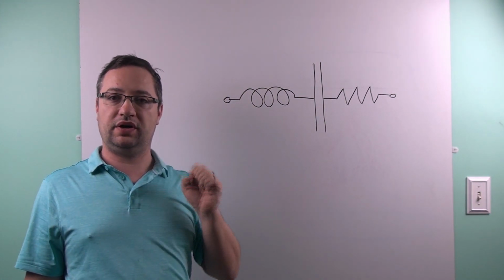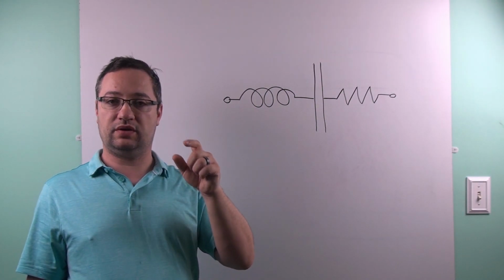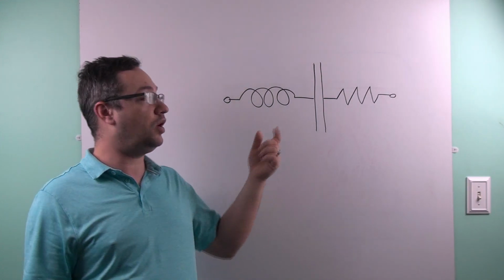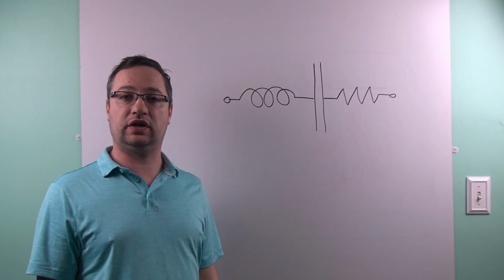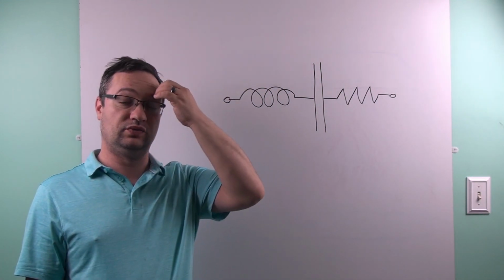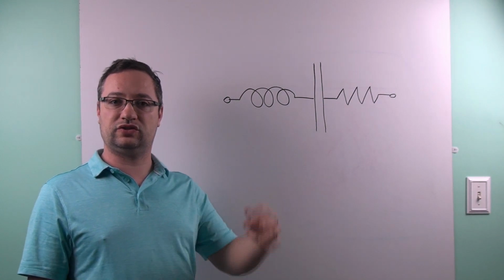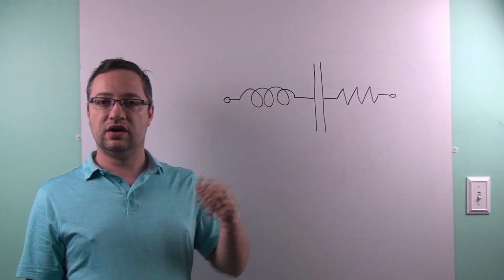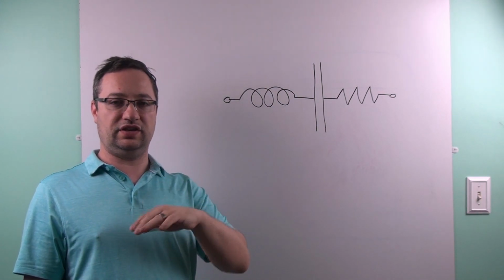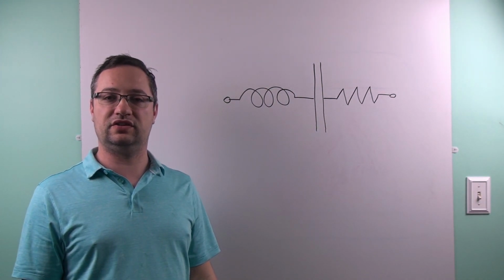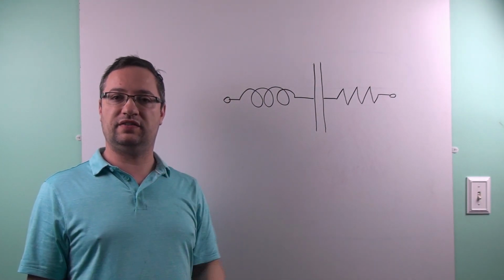Now, from what I said earlier, the capacitor element most of the time is the major part of the model, but depending on frequency, this inductor here can actually become very, very large, swamping the fact that this is a capacitor, and the capacitor starts behaving more like an inductor. But we're talking very, very high frequencies, in the high megahertz, low gigahertz kind of area. But generally speaking, for most of the stuff that the average electronics engineer does, this inductance here can effectively be ignored.